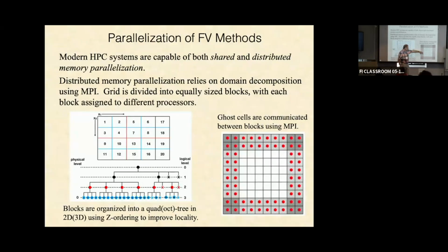But for various reasons, it's generally more convenient to be able to set the boundary conditions using the actual cells themselves. And that's why we use ghost cells. But you could rewrite it in a way that you always have to set specific values of fluxes. That's right. It's a case of convenience.